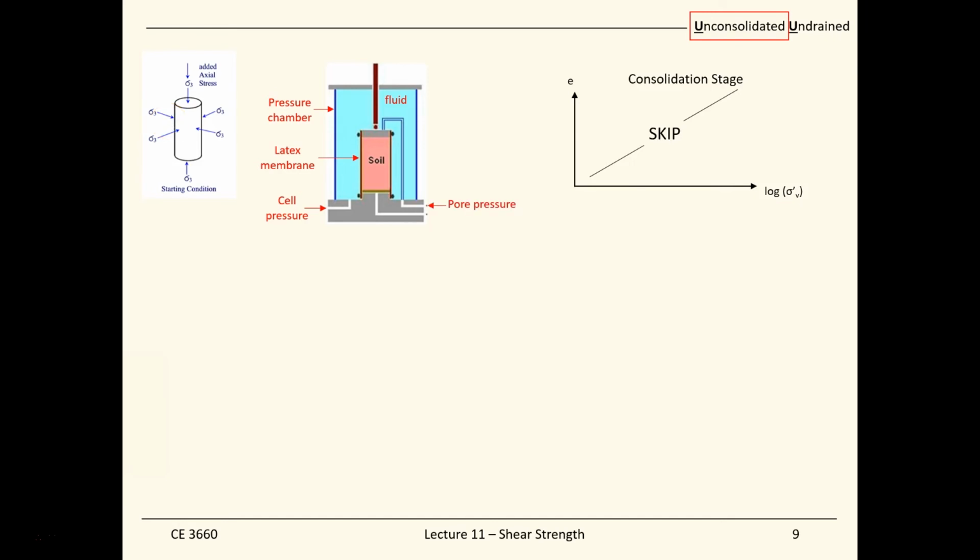And more details on this laboratory setup. There are also connections of the soil to an outside pressure source. This is the pore pressure. So you can apply pressure into the soil, and we can also monitor the water being expelled out from the soil. There's a volumetric change measurement connected to the soil, so if water comes in and goes out from the soil, you can also collect it.